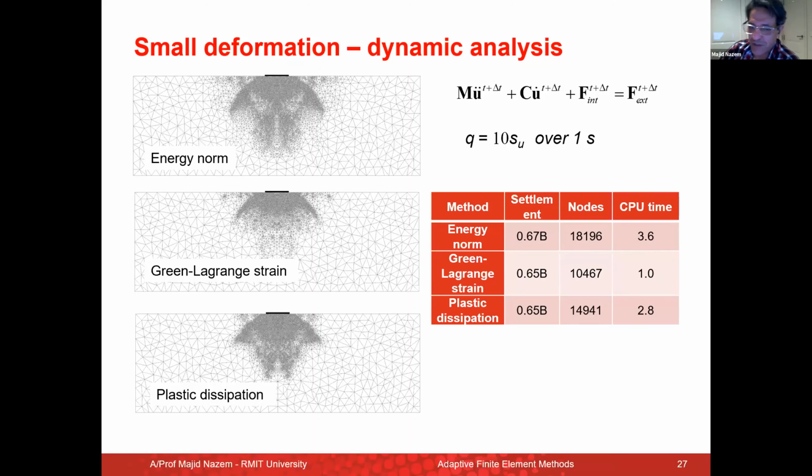So you mean why not generate a new mesh every time? Yeah, if I understand your question correctly. What I'm asking is, why isn't this technique more used than seems to be the case? My guess would be because the mesh generation itself is relatively cheap, especially in 2D. There are lots of routines out there for doing this, and even in 3D it's not too bad. So one of the main complications is, if I'm not mistaken, the mapping of your variables from one mesh to the next, which is not really that difficult either, but which may generate some error.